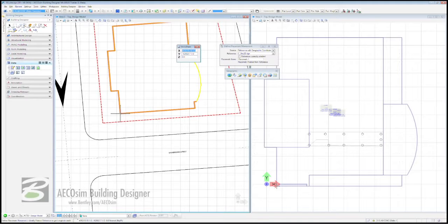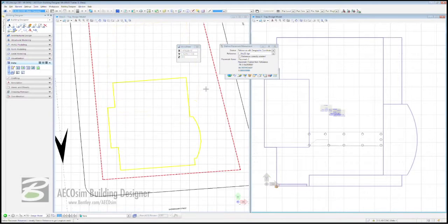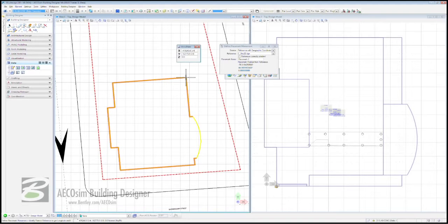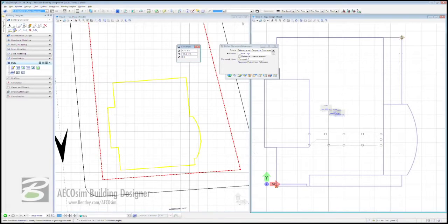So we click once with our left mouse button at the same spot in the bottom left-hand corner of our structure, and then we just click and right-click. We then come to the top right-hand corner and diametrically opposite, and we do the same. We place a tentative point there. We move into the right-hand side where our structure is. We click once, twice with our left mouse button, right click to reset. The more points you make, the more accurate it will be, but 2 will do us exactly for this moment.